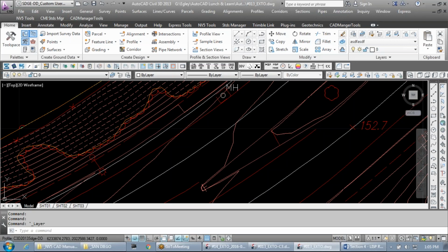So first submittal to my client or to the agency, I'd make a layer state so that my drawing, I can always go back and plot exactly like that point in time. Yes? So what's the difference between that and archiving another file? Like, you know, the layer state is active in your drawing. So you're going to always be working on this file, right?